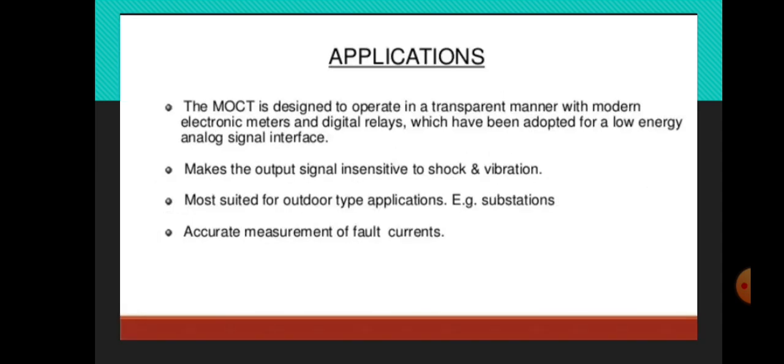The applications of MOCT are: The MOCT is designed to operate in a transparent manner with modern electronic meters and digital relays, which have been adopted for a low energy analog signal interface, makes the output signal insensitive to shock and vibration, most suited for outdoor type applications, example substations, accurate measurement of fault currents.